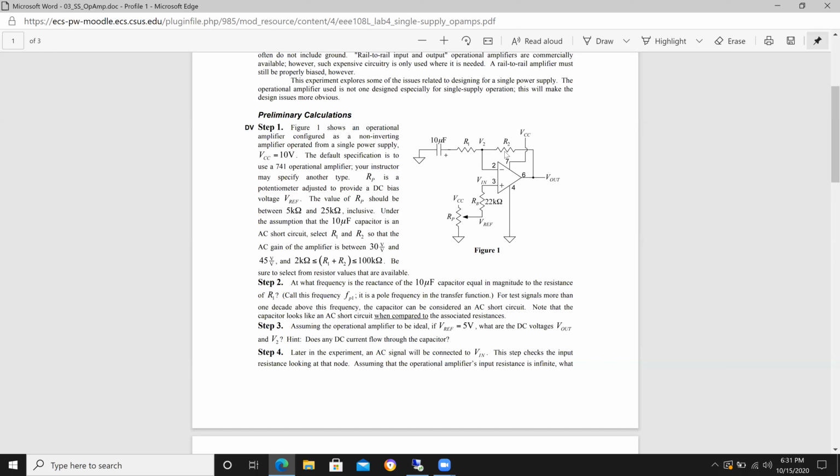But you've got to keep in mind, there's no current going into the negative terminal on this op amp. So therefore, whatever VOUT is, V2 is, right? So we've already established that the gain is 1 at DC because R1 is effectively open. We've also established that there's no current going through R2. So the circuit is acting as a unity gain buffer.